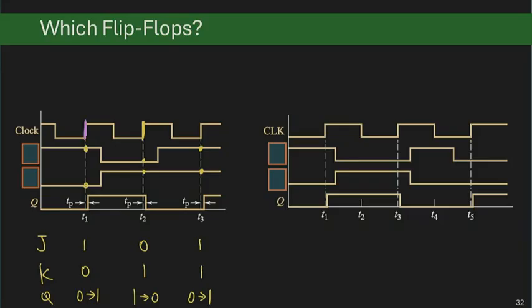Cool. Did you find something? 1 sets it to 1. 0 toggles it. Yes. That's right. And it's none of what we learned, right? 0 doesn't do toggle in both SR and JK, so it's probably some novel flip-flop. It's actually like a typo in the textbook. The book calls it an SR, and they're trying to provide an SR example, but they miserably failed.